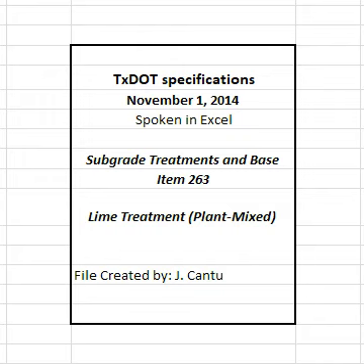Reimburse the department for subsequent mix designs or partial designs necessitated by changes in the material or requests by the contractor. Limit the amount of asphalt concrete pavement to no more than 50% of the mix when treating existing materials unless otherwise shown on the plans or directed. 3. Equipment. Provide machinery, tools, and equipment necessary for proper execution of the work. Provide rollers in accordance with Item 210, rolling. Provide proof rollers in accordance with Item 216, proof rolling, when required.